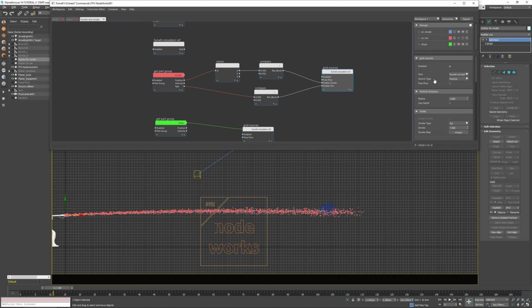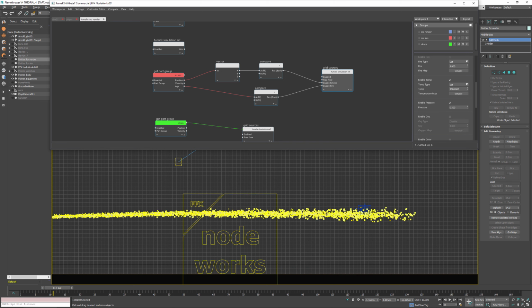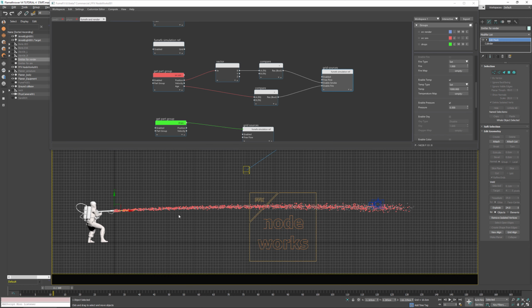For the grid sources, I'm going to use particles. So each particle will be a little sphere with a radius of 2, and the smoke type is set to value 1, controlled emission by this compare operator. Similar goes for the fire, and all those particles here are going to emit temperature 100 degrees. They're going to emit all the time, from those particles that do not emit smoke or fire to the last particle that emits fire and smoke.